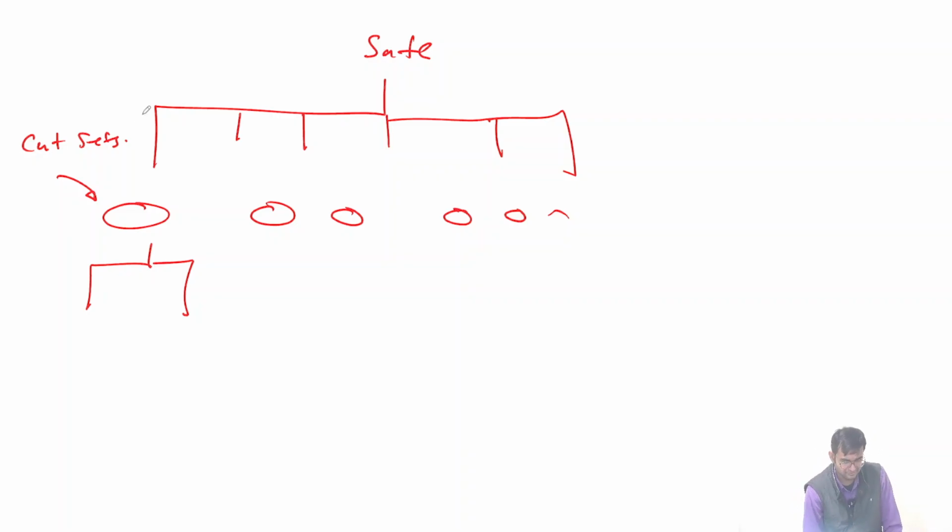I mean, here, this is not safe actually, right? This is PF also. Basically system reliability. But an important point that was raised was that in most cases we will not know how the modes are interacting, whether they are correlated, independent or not, and that is why we will not be able to find out the exact system reliability. Rather we work with bounds, right? And let us see how we can work with bounds.